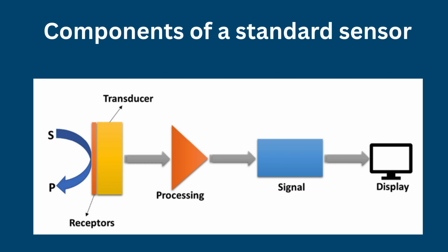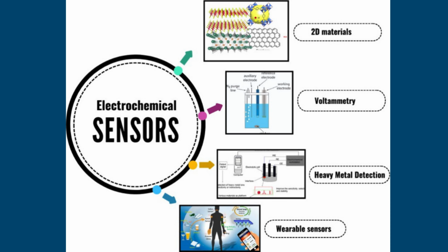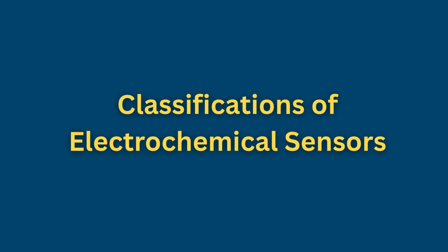Among all chemical sensing technologies, electrochemical sensors have emerged as dominant due to their high sensitivity, low detection limits, often reaching picomolar levels, rapid response times, and relatively low instrumentation costs. These sensors are highly versatile and exist in configurations ranging from conventional laboratory-based systems to miniaturized, portable, and wearable devices. Their primary function is to provide accurate, real-time information about the chemical composition of a system without significantly perturbing the sample. In practice, electrochemical sensors operate by measuring electrical signals generated from redox or interfacial processes occurring at the electrode surface upon interaction with the analyte.